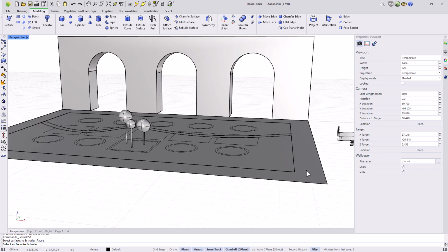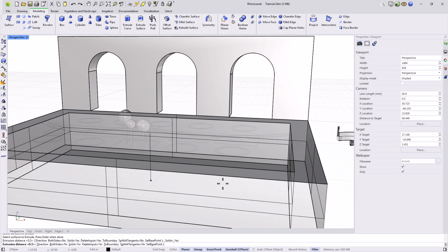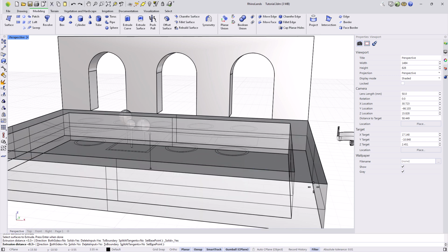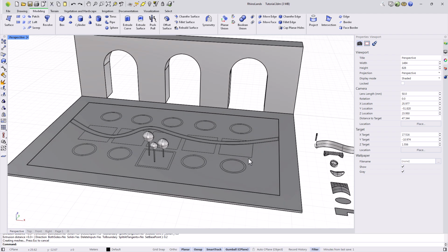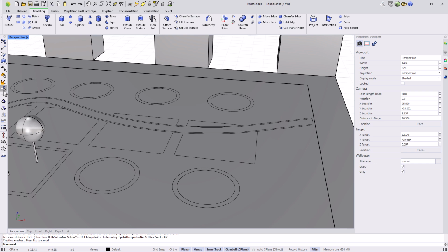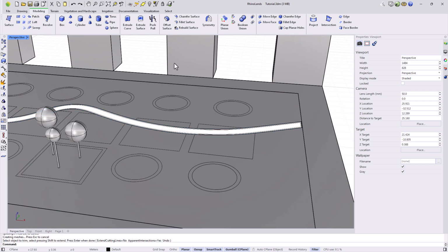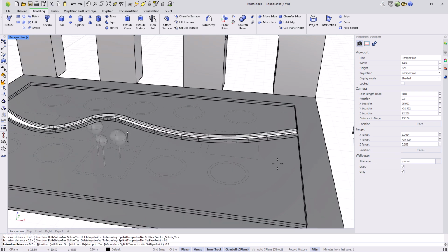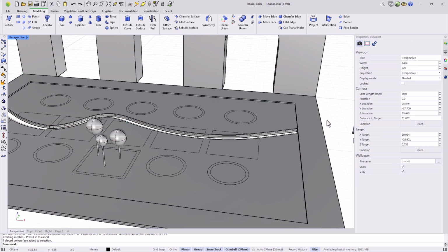This command works the same way, with the difference that the input to select is a surface instead of a curve. We can extrude the surfaces we have created so that they have a thickness. If we select to delete the original, when the new solid is generated, the original surface will also be removed to avoid having this duplicated face. I've given the outer part a thickness of 0.2, and for the inner surface, I'm first going to trim it to leave space for the water pond, and then I'll extrude it with a thickness of 0.3 and move it. To create this small elevation at the top,